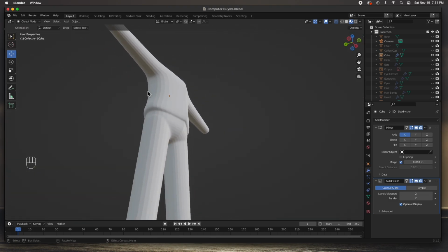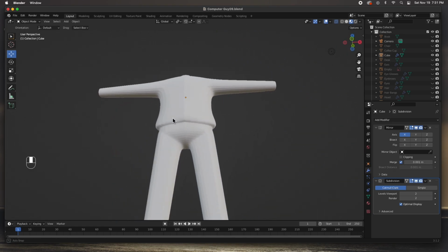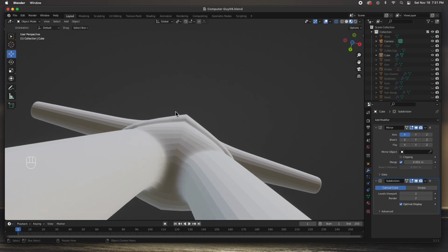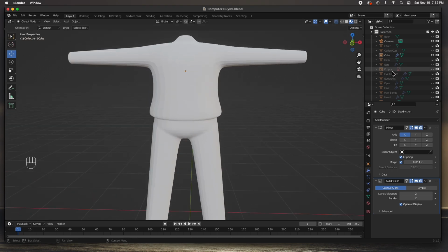I like it. We could fix this little V by going here to clipping and merging distance. There. We just enlarged it a little bit. And then that gets rid of that. So let's go ahead and add the head again. Let's turn on the head again.